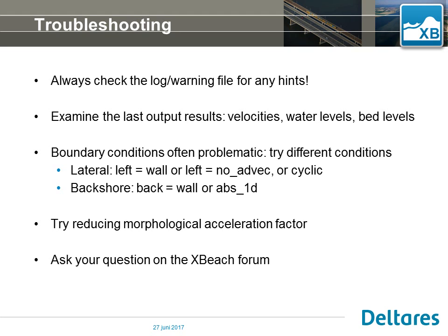Also, instabilities in the model can be caused by having a morphological acceleration factor, a MOR factor, that is too high, which leads to unrealistic bed level change within a time step, and then makes the model explode.